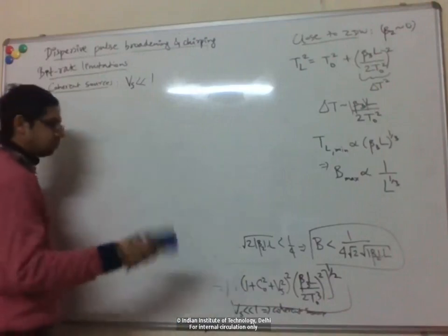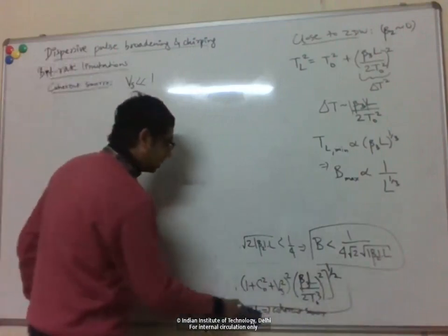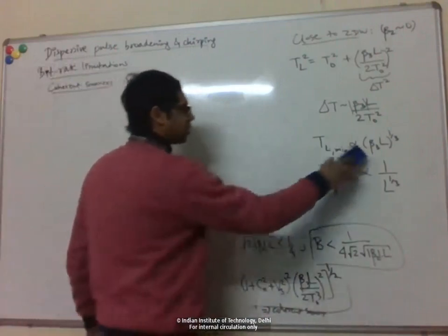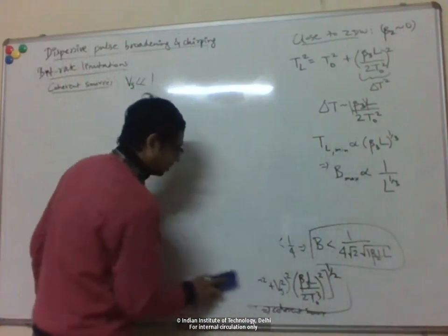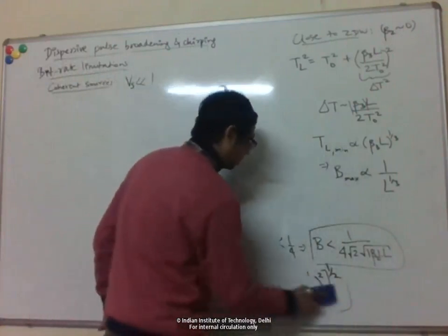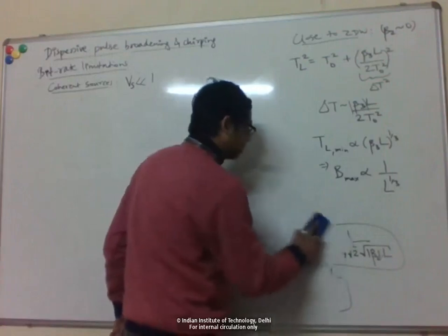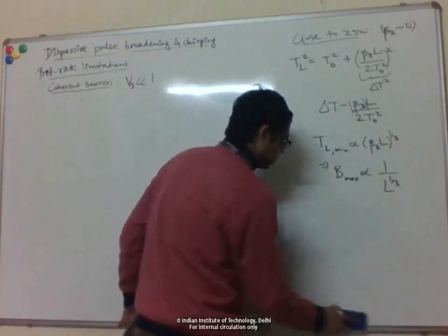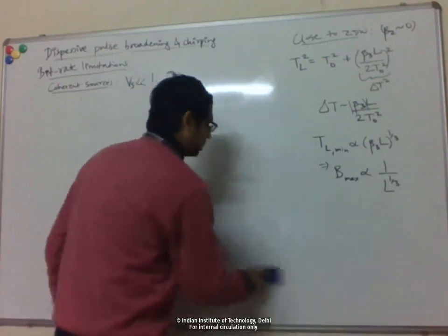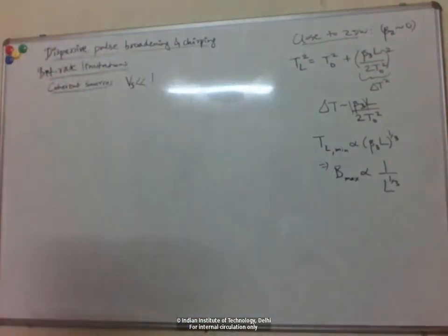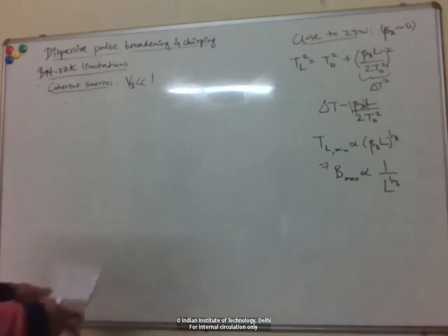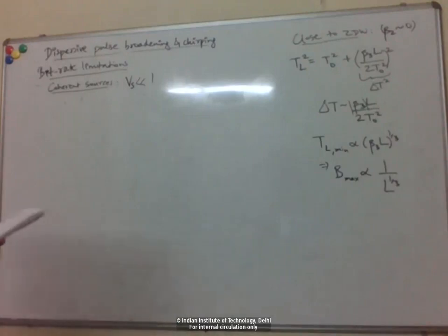So for the same link length, the maximum data rate will be for the case when you're operating with coherent sources at the zero dispersion wavelength. The next best would be coherent sources but away from zero dispersion. Next best would be incoherent sources at zero dispersion, and the lowest data rate for a particular link length would be for incoherent sources and also away from zero dispersion.